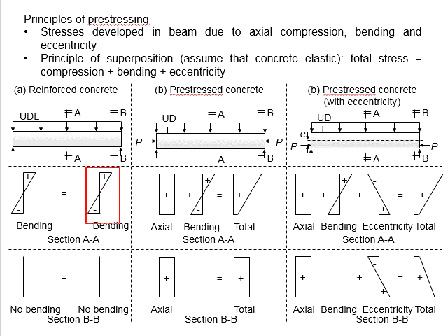Therefore, the final stress within the section will be the same as the bending. As for the support, there is no bending moment. With that, the beam is assumed to have 0 bending stress and there is no external load, so the total stress will be zero as well.